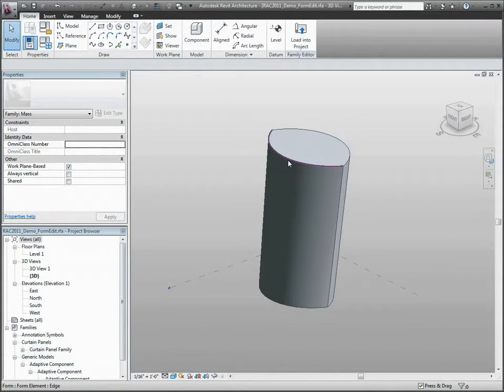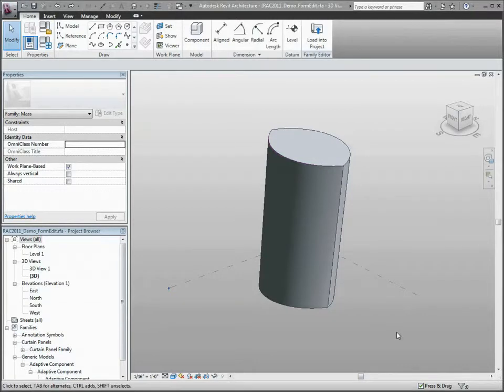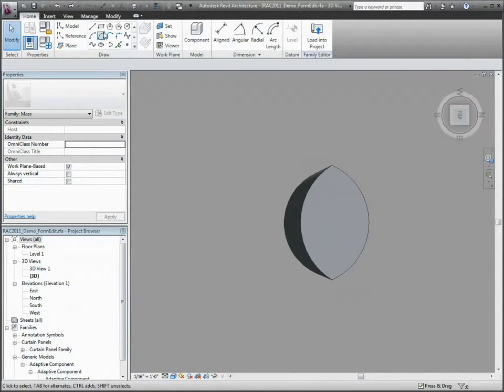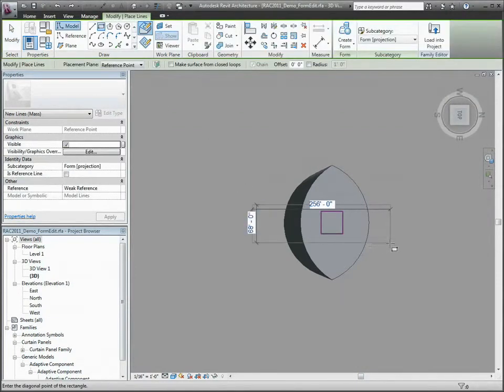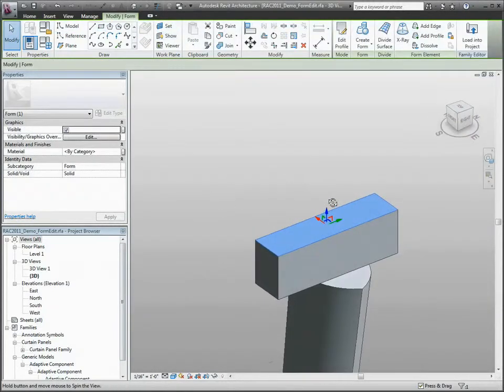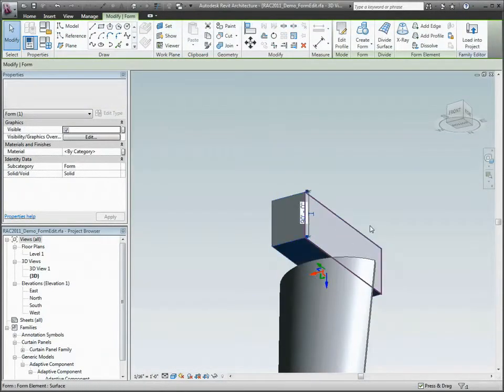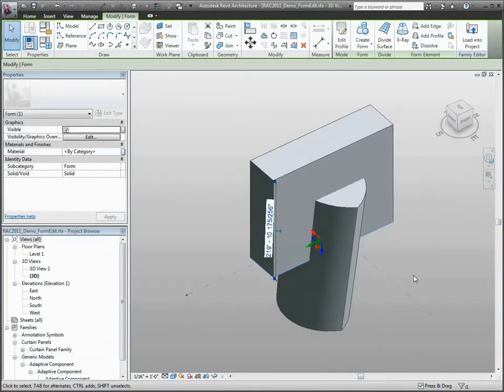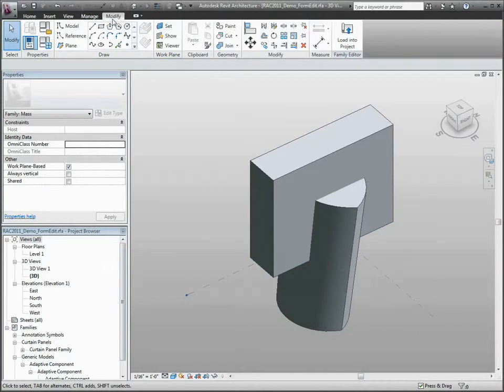This command works for all types of form sketches, including but not limited to revolve profiles, sweep paths, and loft profiles. In the past, only voids could be used as cutting elements for Boolean operations, and it was difficult to access them again for further transformations. Now solids can be used to cut other solids, so that when the cut is executed, geometry from both forms remains visible. If you need your cutting elements to remain as part of your design, you can do that.